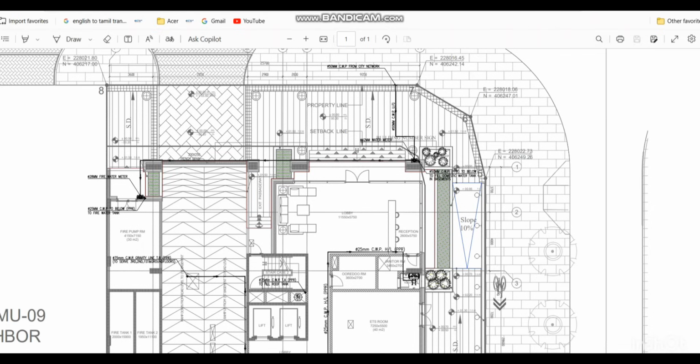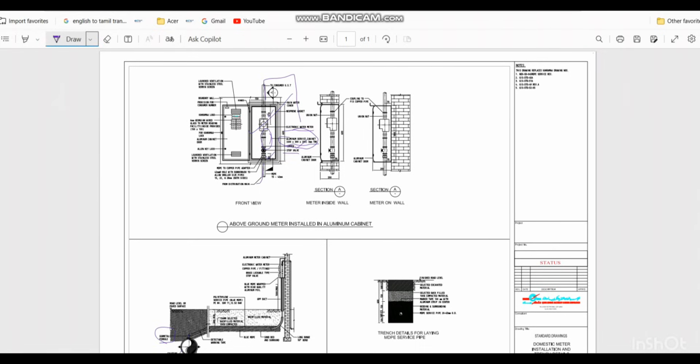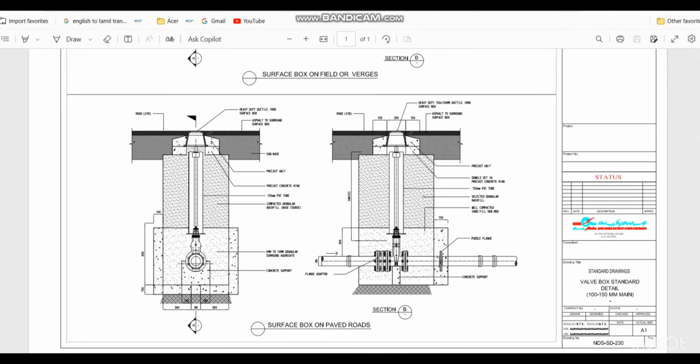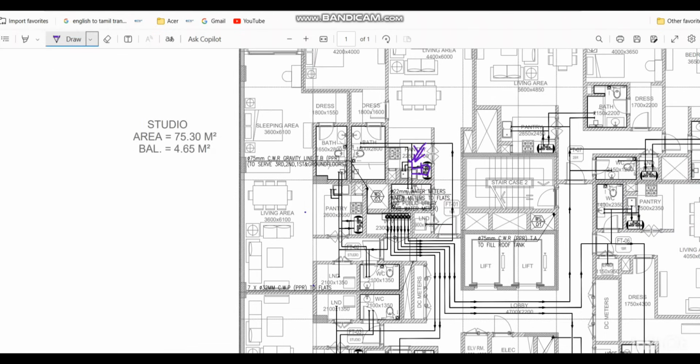So finally, in this project, we discussed how to perform the tie-in with existing connection by referring to the details. Then we referred to the water meter cabinet details. After that, we referred to the isolation wall, how the buried isolation wall will be installed in the project. Then we referred to different pipe materials for underground, above ground, pipes in soft areas, and pipes in the roof area. Then we discussed the insulation special concept, and the normal PPR and PPR CT pipes.